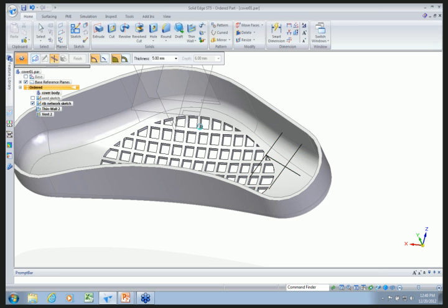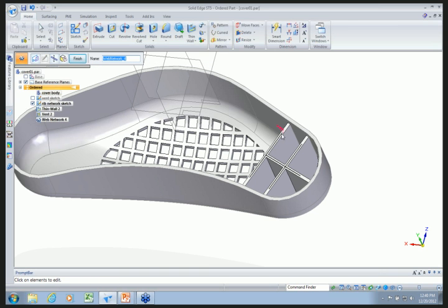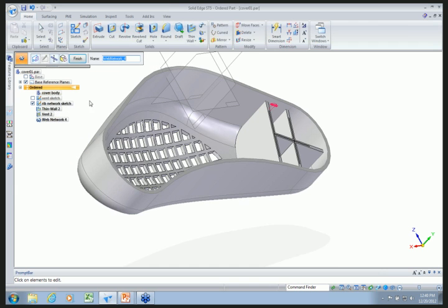So I'll go ahead and place that. What the extend profile does, you'll notice that our lines don't go all the way to the edge of the part. So extend profile is telling it, go ahead and send these lines to the edge. That way you don't have just part of it sitting out in the middle. And with thickness, or the depth, that just sends it all the way down to the bottom of the part, wherever that is.